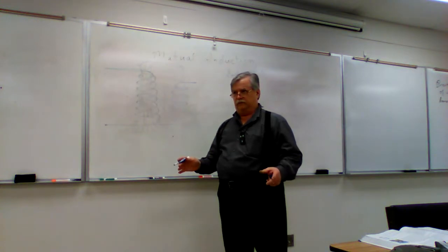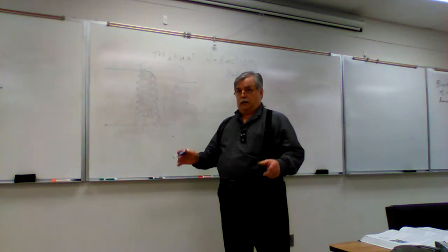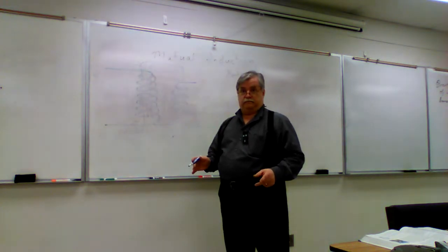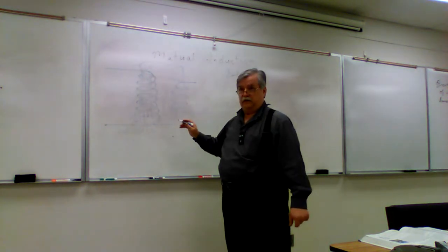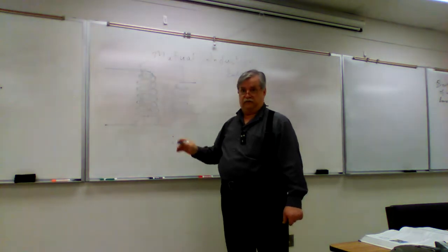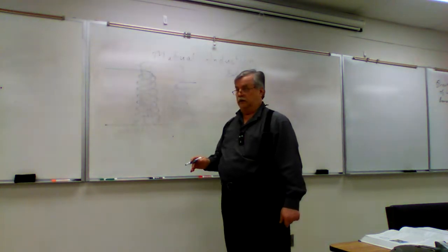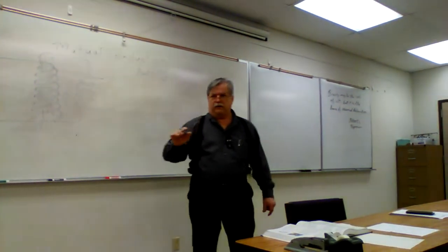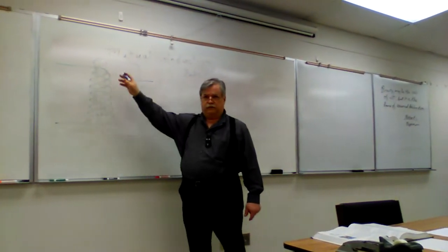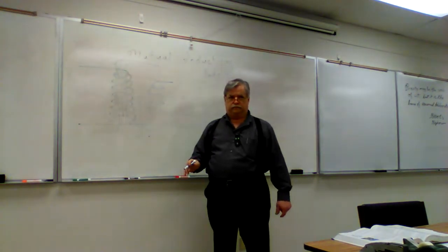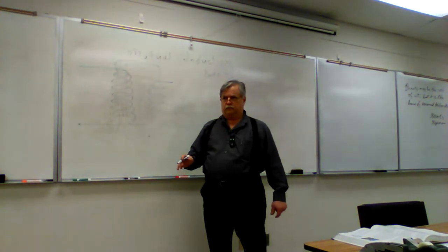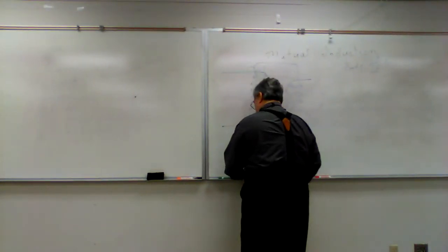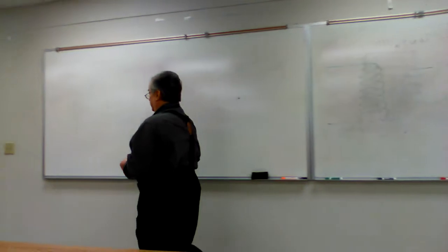100% efficient. Okay? But they can be made close enough that the difference doesn't matter. They can be made significantly greater than 99% efficient. Okay? Think about this. What's going to be one of the primary losses due to this transformer? One of the primary loss mechanisms for a transformer is called eddy currents in the core.